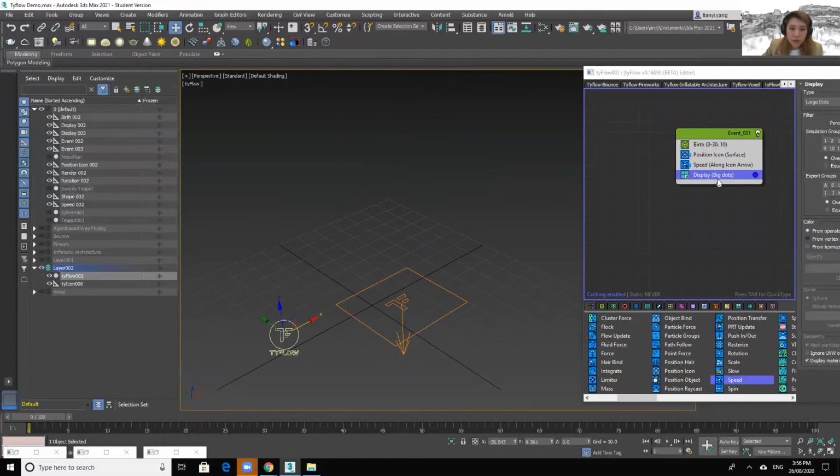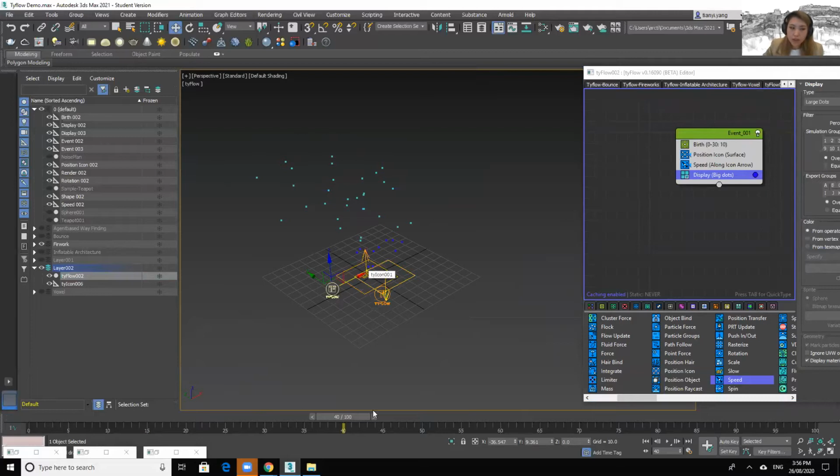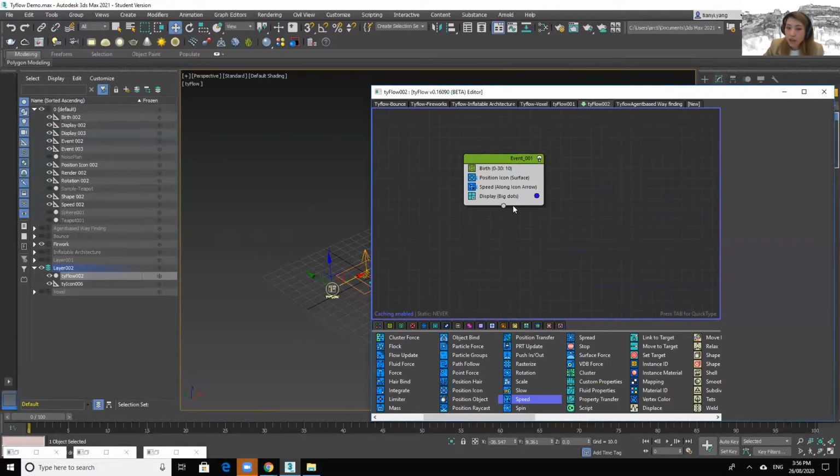But if you have a close look, as the firework we created before, it's not really following completely the arrow icon direction. It goes a little bit random to the side and starts dropping down. So let's do the dropping down first. For the dropping down, we need to add some gravity onto the icon. So by doing that, we need to add a force.